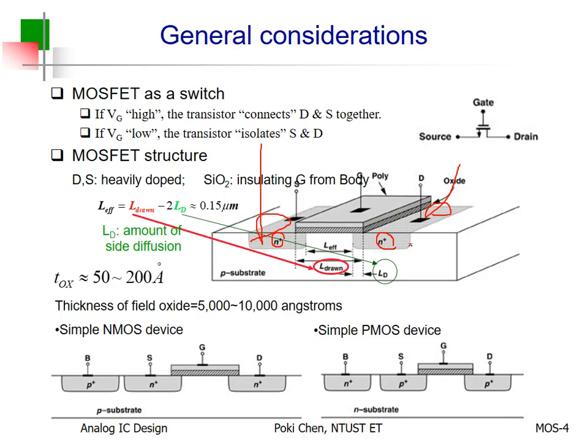Okay? And then there is the gate, the controller to control the current conduction on or off, in theory, and the main component, the channel. It needs to be isolated. Okay, how to isolate your gate from your channel? Very simple. We have another layer here. See? It is the so-called silicon dioxide. That is a very, very good insulator.